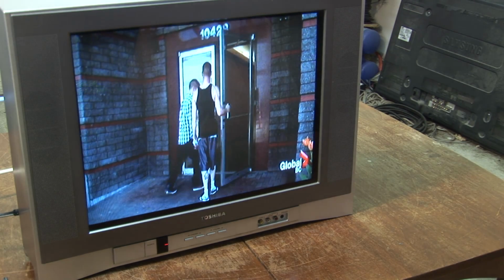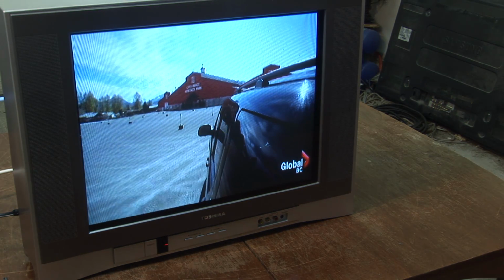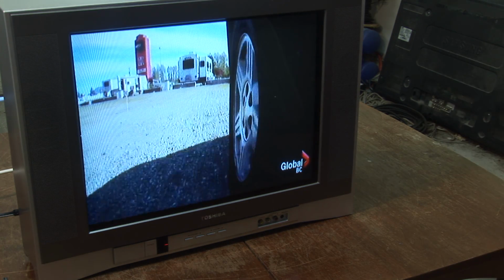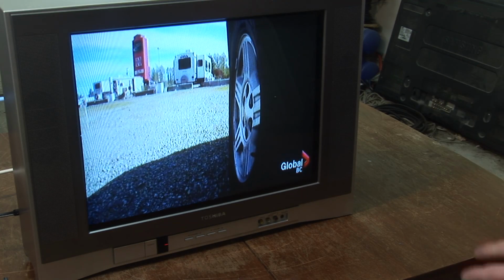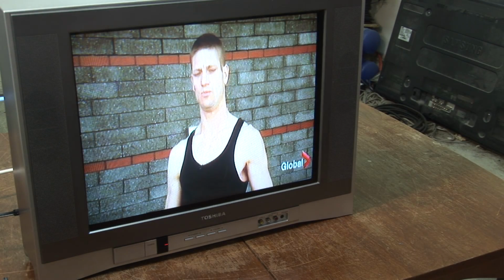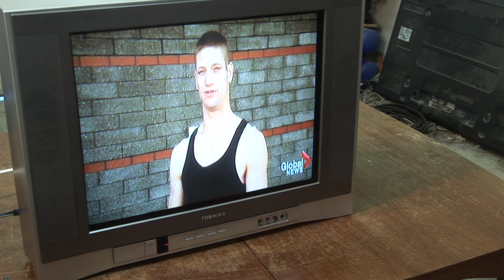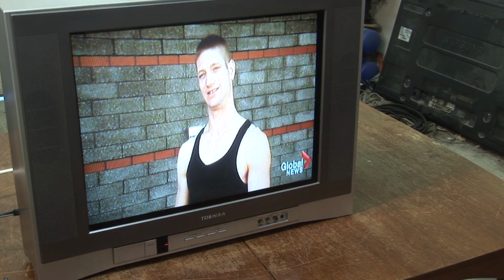And you know what? The best part of all, they're free. People are giving these things away. They want rid of them. So there you go. That's how you fix a CRT with a vertical problem. 2 capacitors in the bootstrap. We'll review which ones failed.